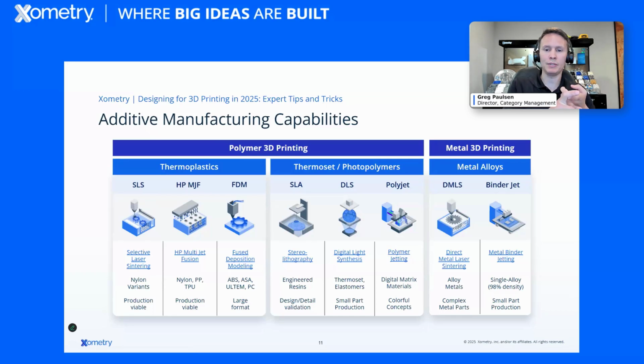Under plastics, we typically have thermoplastics. So something like ABS or nylon, where when I apply heat, it goes into a liquid state, it cools, and now it's a new shape. That's going to be a thermoplastic print. Thermosets. I think if you've ever had a cavity filled where they have to shine that UV light in after they put that liquid or paste in there, that's going to be something like a thermoset material where it hardens and catalyzes with exothermic reaction. So think about resin photopolymer printing, for example, very good example of a thermoset or resin-based 3D printing process.